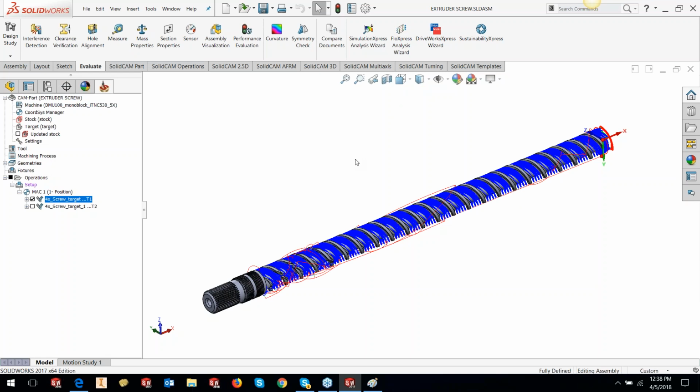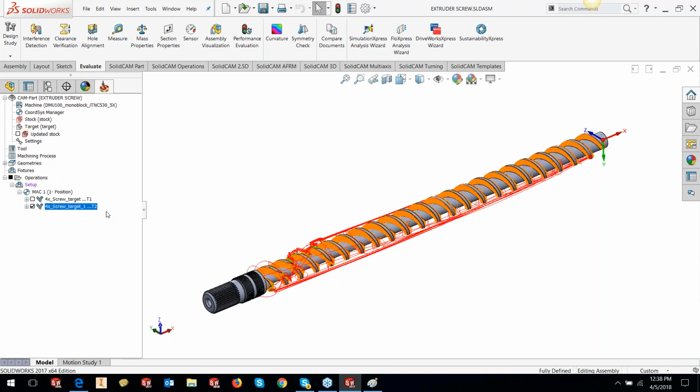You could be spending few hours on this part trying to figure out how the tool path would come out using a generic 5-axis. Whereas just selecting the part, selecting the axial limits, selecting the tool, selecting the depth of cut and the side step would take you not more than a minute to define and about 12 minutes to calculate. And the same thing can be done, or finishing can be done in approximately another 10 to 12 minutes, just by selecting a different tool, different down step, and a different side step.